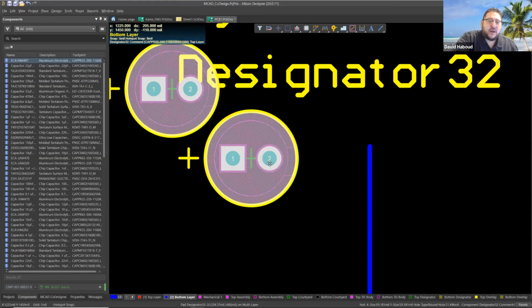You could see here, because we have a component courtyard associated with this component, you can see really here perfect selection of the component. So previously you would get a DRC error for the placement of these two components right here, but you no longer have this issue. And this will also help with the placement of other components.